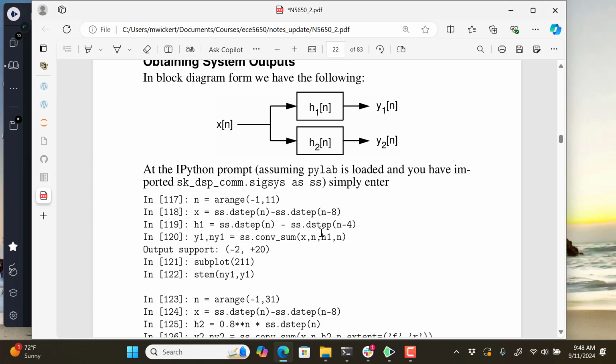We were talking about it as an analysis tool, and when you use it, you get to tell it the X signal that you want to convolve with the Y signal, let's say, or H1, and then in order to get an axis for plotting the output that makes sense, you have to give it an axis of integers that matches the X array and an axis of integers that matches the H1 array, and then what comes out of this function is exactly what you want.